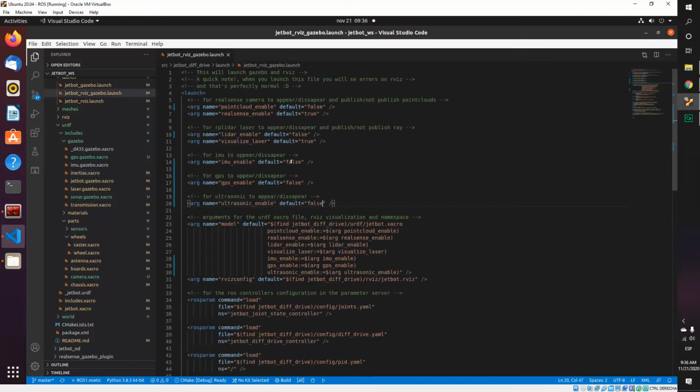The next thing is that if you see your model drifting, it is about the physics. So you check your friction parameters, the inertias, the center of mass, the collision, everything related to Gazebo, because it's the simulation that is failing. And check also your inertia tags, that you have your inertia.